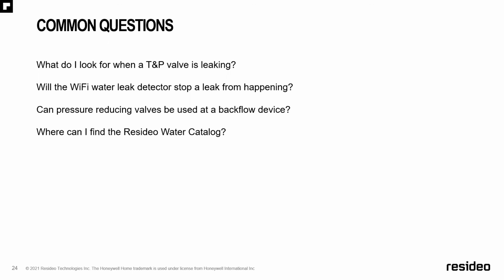The next thing I would look at, if that's not an issue, is the general age of the water heater. Maybe it's beyond its life expectancy. These days, tank type water heaters can last anywhere between 5 and 10 years. I know that's a pretty big range, but we all know water conditions are different everywhere we go. So check the age of that tank, make sure that you are in good shape.